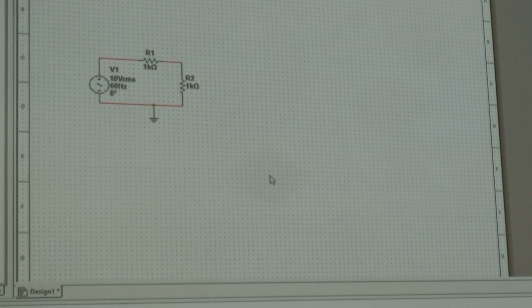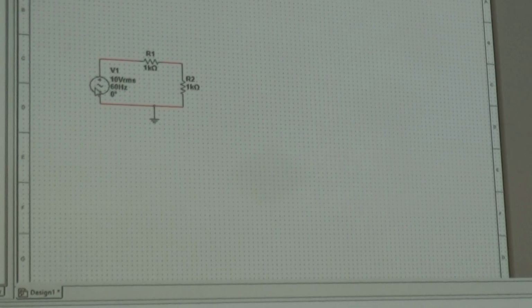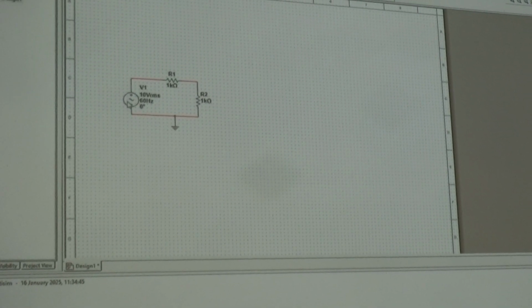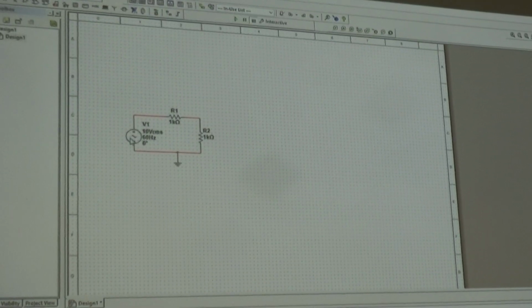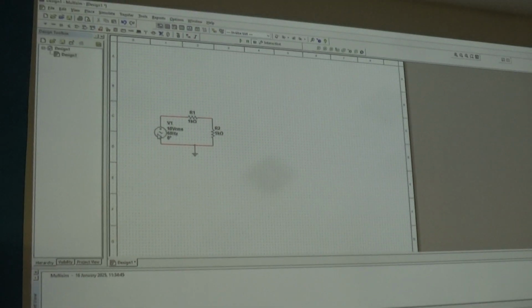It's going to be much more meaningful if we can actually see the wave, right? Because we know it's there, we know that that signal generator or the AC source at the beginning there is making this wave for us. But now we've got an added complexity because we're putting it through a potential divider. Now remember what a potential divider does. It means that we can generate a voltage on the output as big or as small as we want. But not only can we do that with DC, we can do it with AC as well.